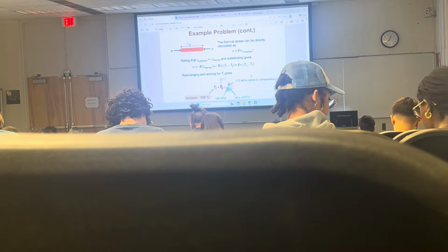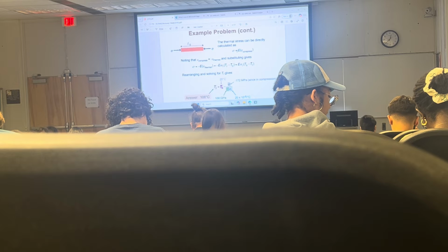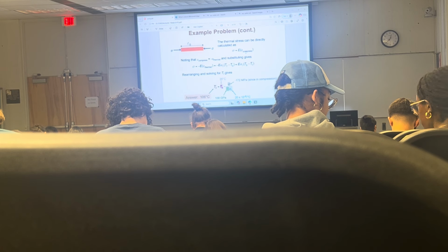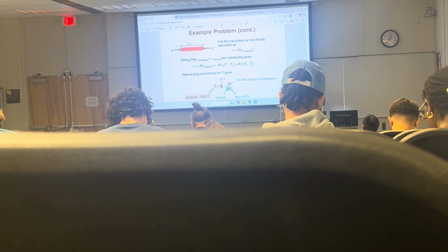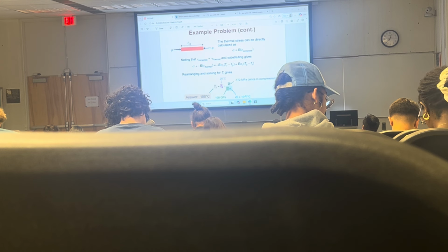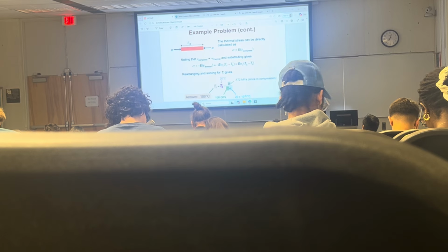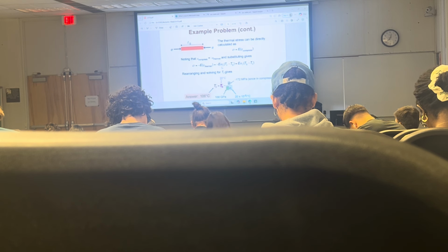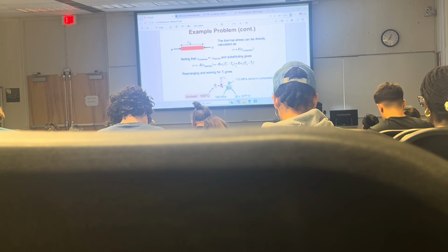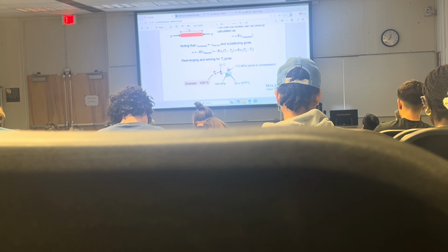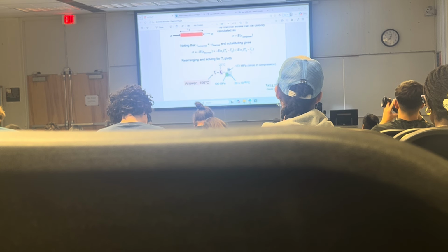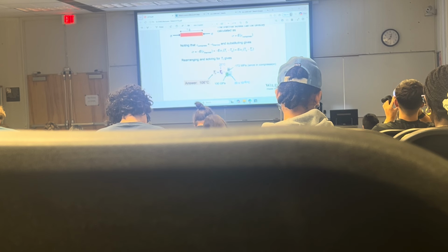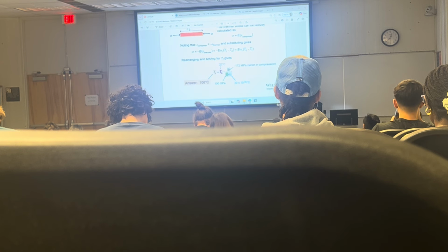So we can write that the stress is equal to the elastic modulus times the compressive strain. And we put all those equations together, get minus the elastic modulus times the thermal strain, so minus E times alpha L, where alpha is the thermal expansion coefficient, times delta T. And then we need to solve for the temperature. This T sub F is how hot it needs to be, right, from this equation.